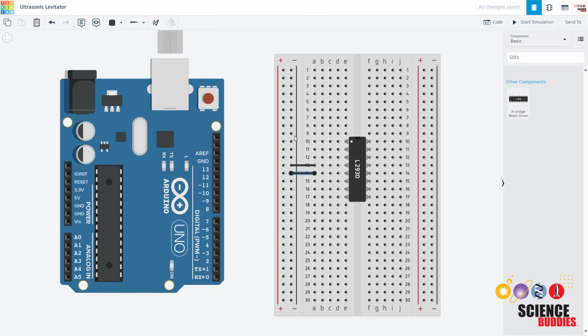That is the bus marked with a black line, blue on some breadboards, and a minus sign next to it. Note that the left and right orientation of your positive and negative buses may be switched depending on the breadboard you purchase, so don't go with absolute left and right here. Go with whichever one is marked as minus on your breadboard. I'm going to do the same thing over here on the right.